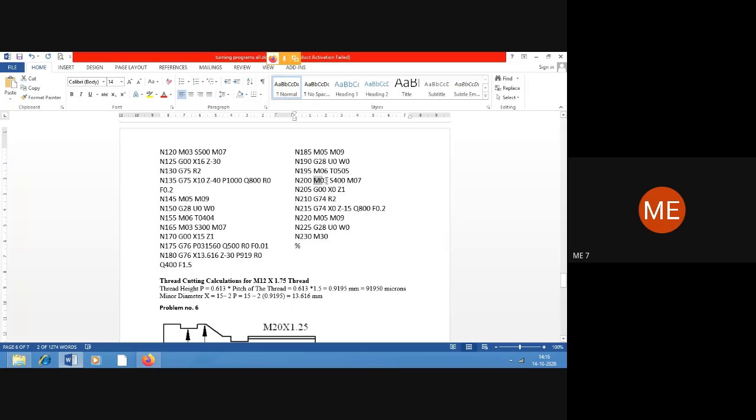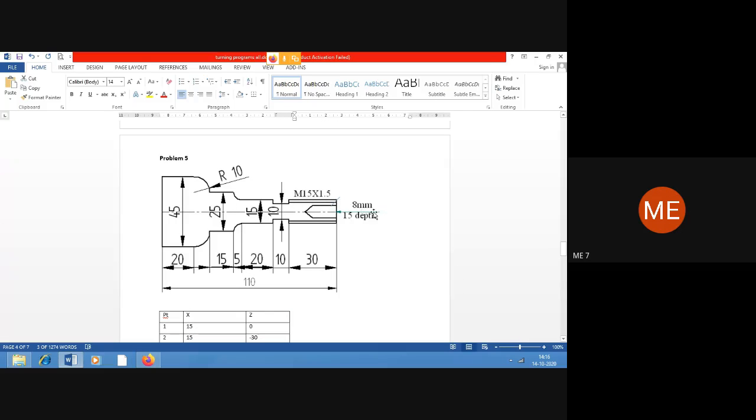So now start the spindle M03, S is going to be 400. Okay, start the coolant, get the tool at the extreme right hand corner. We want it over here, just like this arrow mark that has been shown over here. So we want the tool which will be fixed to the tool holder, which will land in horizontally, right? So here the tool should first come from its home position to a coordinate where we need it, in this particular place.